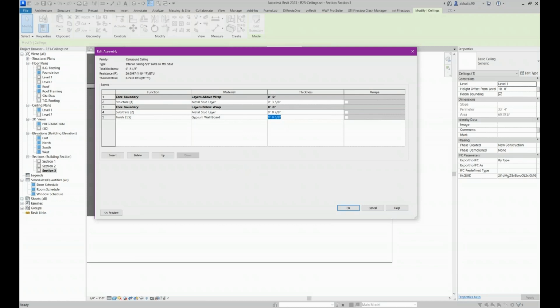Unlike walls, these thicknesses don't really matter much when it comes to ceilings and floors. When we go into the templates, I'll show you, but you're specifying the thicknesses yourself, not telling it to follow a value here. That's because floors and ceilings can be drawn by just drawing marker lines. You don't even need a ceiling or floor element.